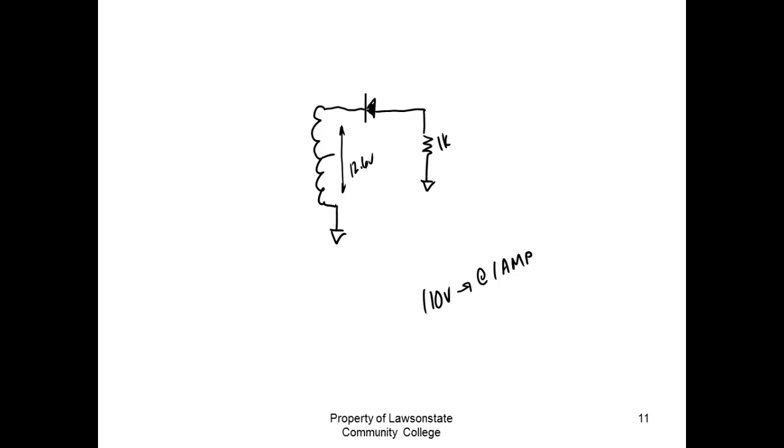So what output should we expect? First of all, we're going to calculate VP because these are RMS values, right? I'm going to take 12.6 and divide it by 0.707. What does that give us? Okay, 17.8 volts. Now that's peak. It's not peak to peak. But in power supplies, we don't need peak to peak, right? You understand that? All we need is peak.